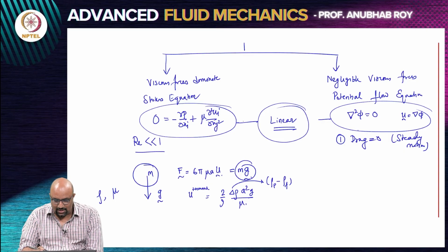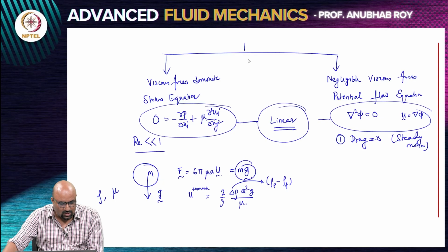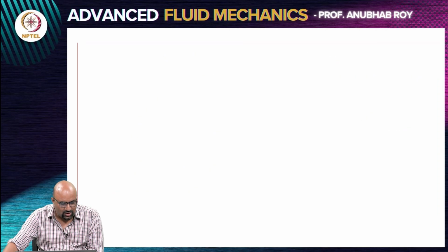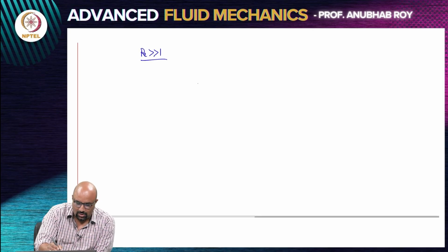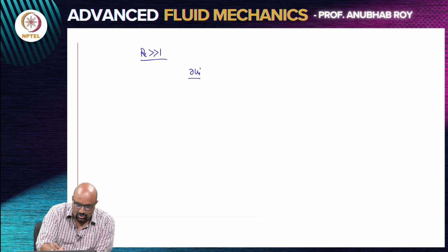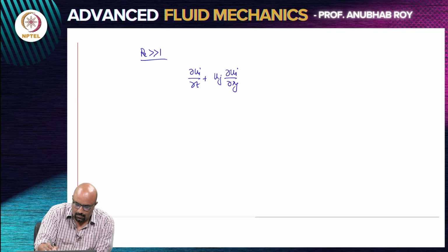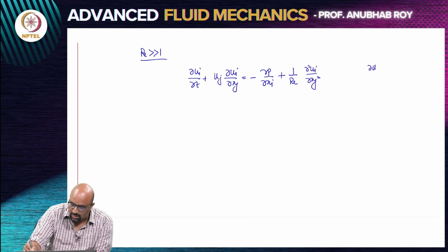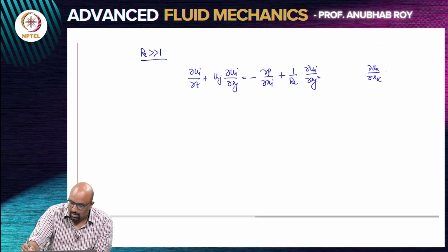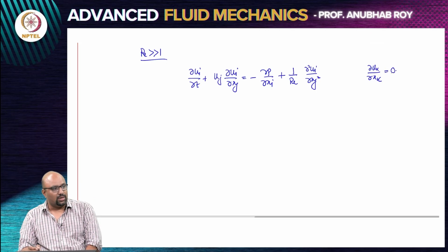So, this is one of the two regimes which are extensively studied. But what about scenarios with very large Reynolds number? Going back to our equation now, in the non-dimensional form, this is our non-dimensional Navier-Stokes equation, and obviously all these equations are accompanied by the equation of continuity, so we are dealing with the incompressible Navier-Stokes equation.